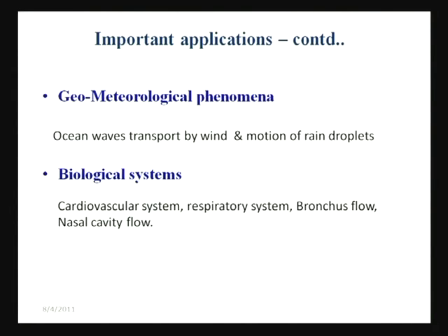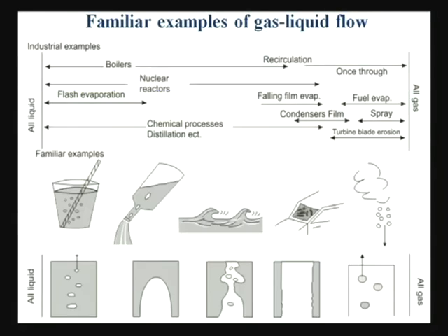But if we have to give a unified approach to this type of study, then we have to present some unifying principles. The first thing is we have to identify, as I had discussed in the last class, how multiphase flow is different from single phase flow. In single phase flow, it is either laminar or turbulent. We have to find out whether it is laminar or turbulent, which is already a very well defined technique. Once we know it, there is no problem at all. In this particular case also, we have to know the distribution of the two phases.